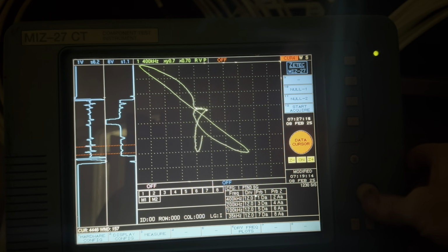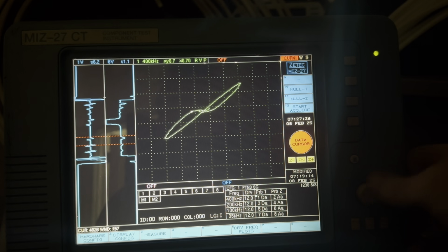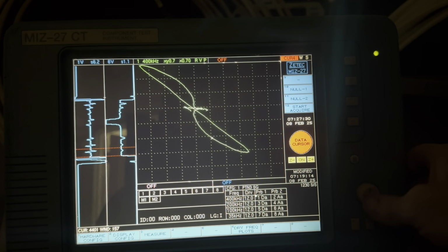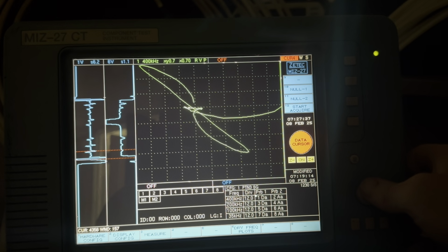So that's a lot of word salad there, but bottom line is when you calibrate and you put your 100% signal to 40 degrees and you see your 60% come in around 100 degrees and your 20% comes in around 140 degrees, that's a pretty good setup for channel 1. You just want to make sure that when you scroll into that 100% that it starts down and to the right, which it does. If it starts up and to the left, that means you have your rotation 180 degrees out. Now what I'm going to do is flip through the channels.